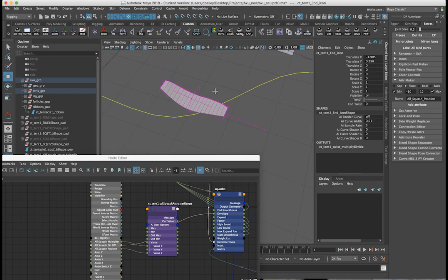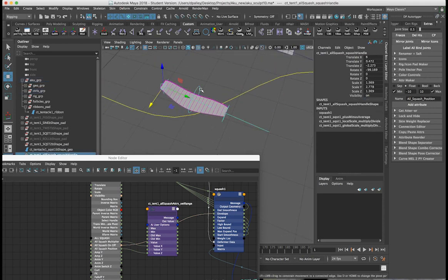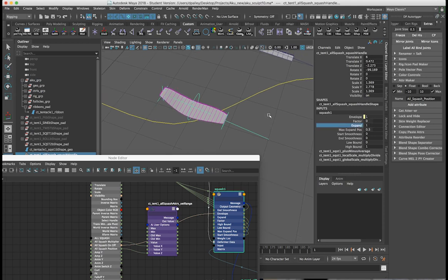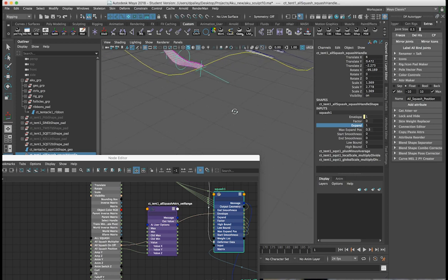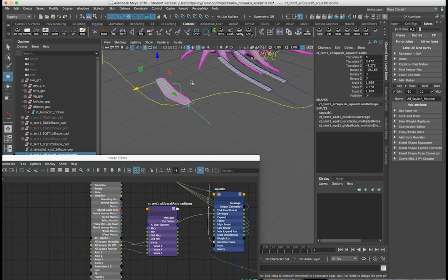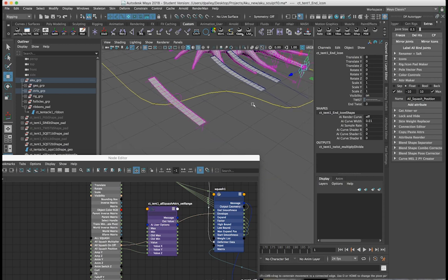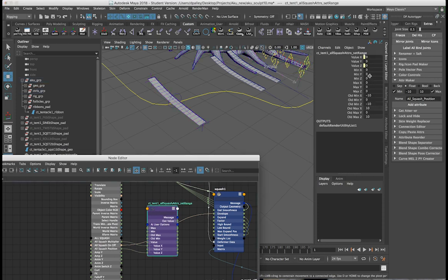So if I show the squash here, and I click on the handle, and I click expand, well, maybe, you know what it is? I directly connected the attributes in. So once it does that, it kind of negates the attributes here. So I gotta just connect these in. But just know, and you'll see why. We're gonna stick with a min of 0 and a max of 2.